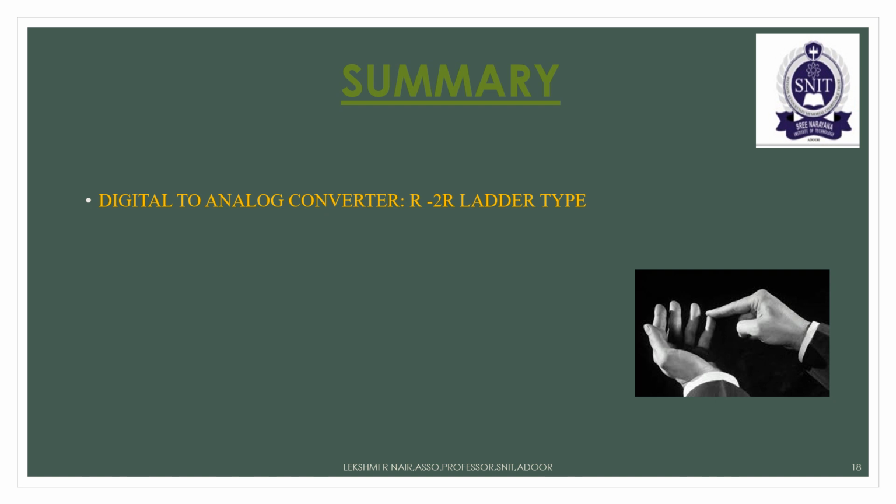Then we discussed about 3 more examples, that is 1 0 0 0, 0 1 0 0, 0 0 1 0, 0 0 0 1. In all that cases we have discussed about the possible analog output voltage, and then we discussed about a parameter known as resolution, and its equation is 1 by 2 raised to n minus 1, where n represents the number of bits.